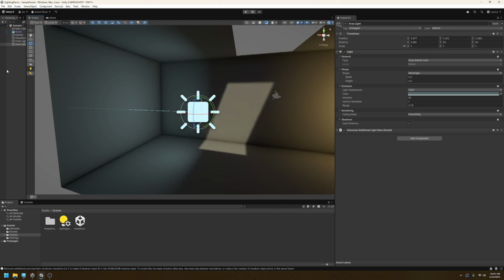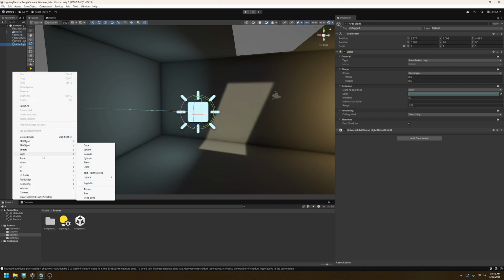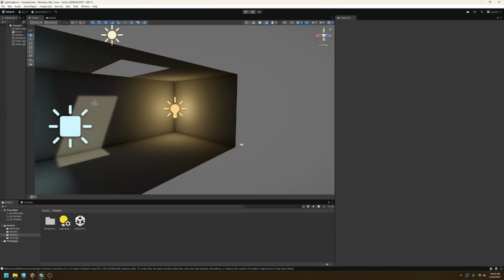I am not going to go over how to use the spotlights. You should basically never use the spotlight. This goes for Unity or Unreal unless you are literally making a spotlight, like a street light that needs a very focused light pointed. Don't try to light spaces with spotlights unless it actually is a spotlight. The whole point of that is it's an angled light that gets that sort of look. You should be primarily lighting your spaces with the directional light, the point light, and area lights, and the spotlight is only if you really need that really focused beam of light. Otherwise, these other lights are going to get you pretty far.